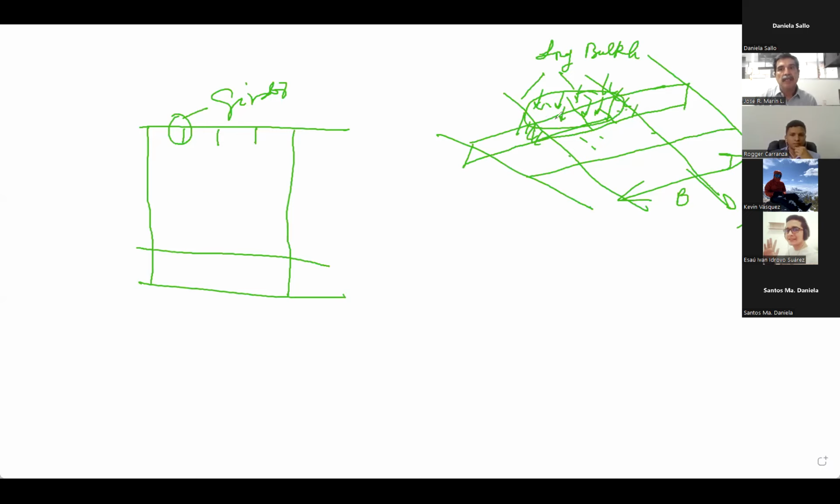So this is the span, the length of the beam. Now, for the loading, you have to consider the spacing, and that's the spacing here. So you consider the spacing and the pressure in order to calculate the force per unit length on the girder. And for the length, you go from here to here. That's L, to analyze the bending of the girder.